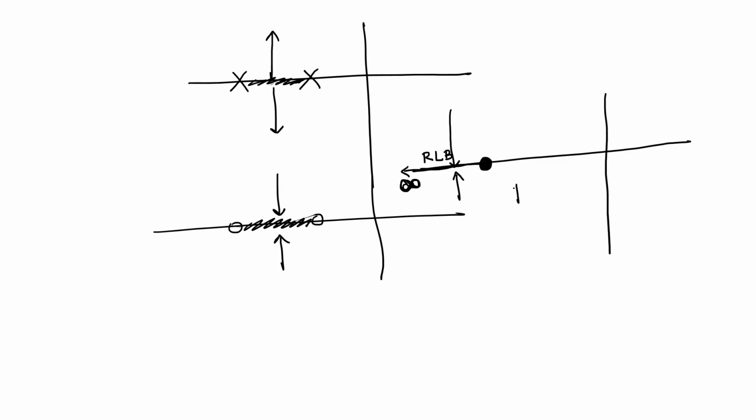The condition is that the number of poles should be greater than or equal to the number of zeros. This third case, you got my point? Whenever a zero is there, and to the left of that zero a root locus branch is there up to infinity, there must be a break-in point if the number of poles is greater than the number of zeros. Clear the third one? Yes, sir.